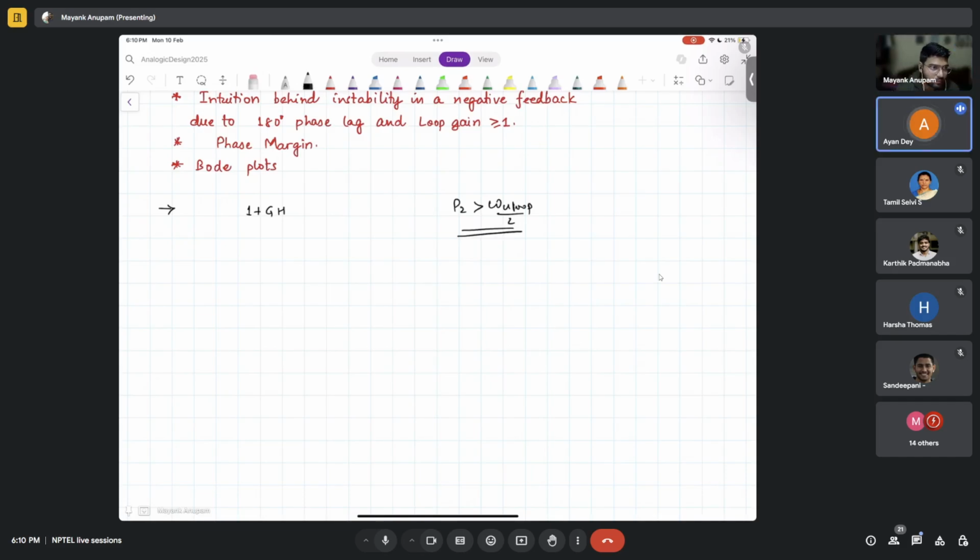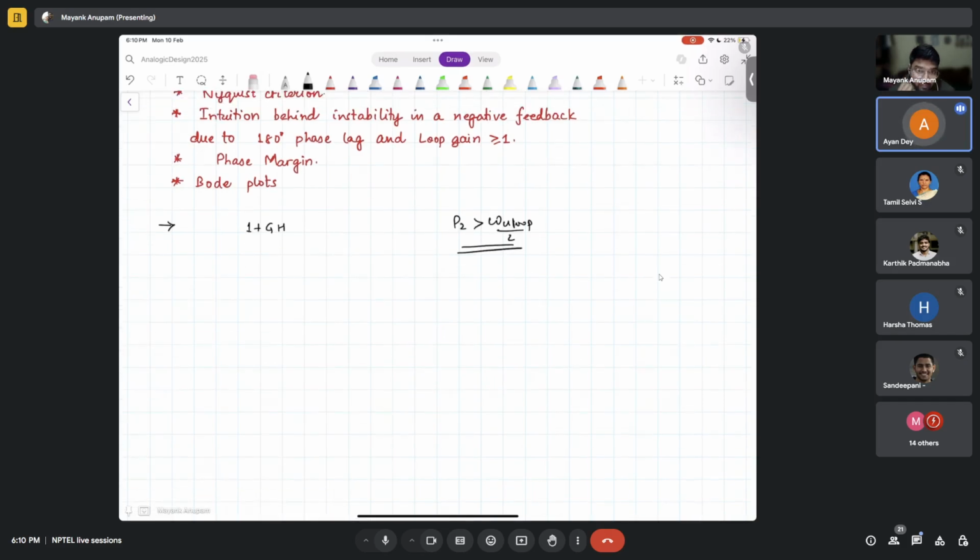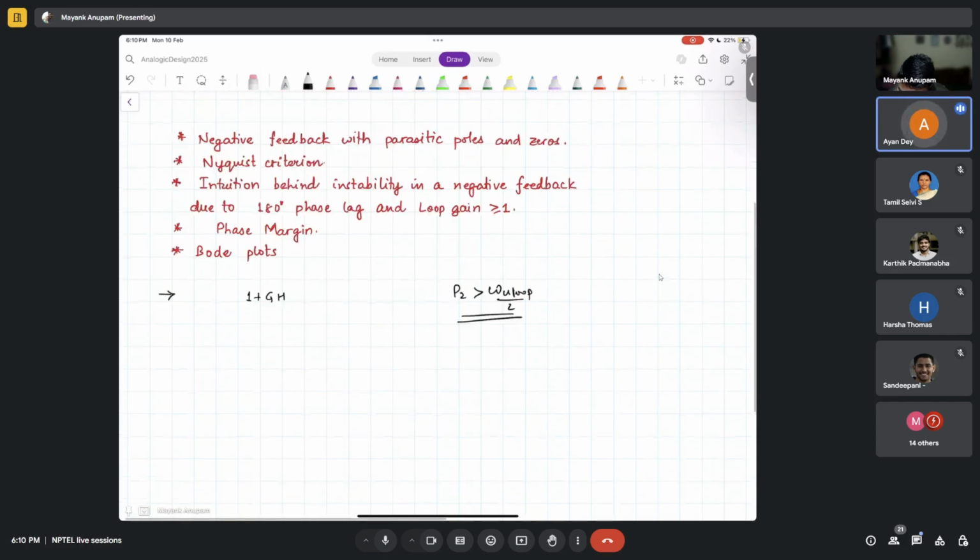Got it? So when we go for the root locus method, here only three poles are there. So we can say that one pole is going along the real axis to the negative real axis, and two poles are going from the point of convergence toward plus 60 degrees and the other one will be minus 60 maybe.